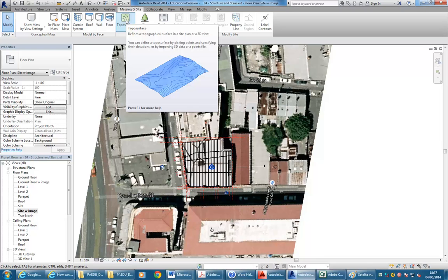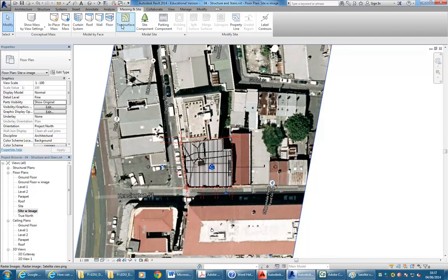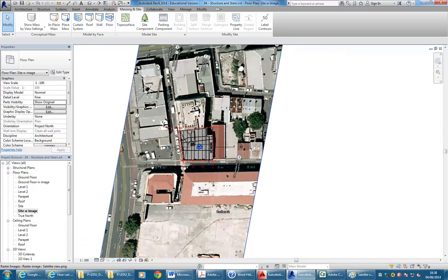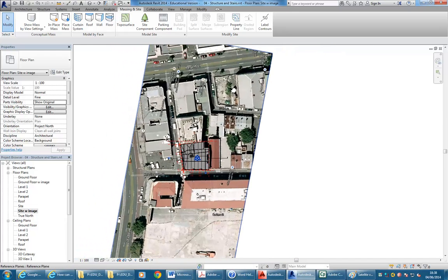So just think of it like something wrapping the whole world, or everything that's considered to be your ground. So whether it's water or road or footpath or anything like that, just do it all as one surface and divide it up later to the separate materials. The major problem people have with topo surfaces is trying to make the separate elements separately when that'll make it fall over.